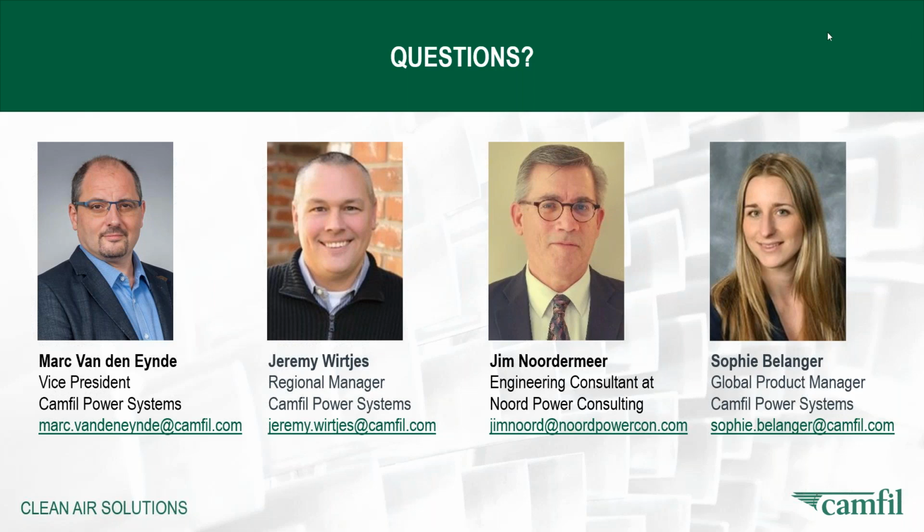So the analysis is probably made by assessing how many operating hours the engine runs, what the current environmental dust concentration is on that specific site, and what experience from the past has shown on fouling and power output losses. Based on that, the recommendation probably came out that the E11 is the best payback for that specific customer. So it's really a local assessment that has been made in this case.